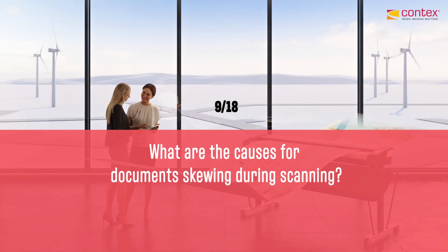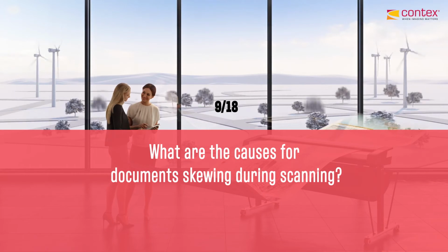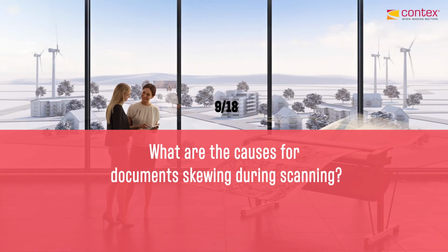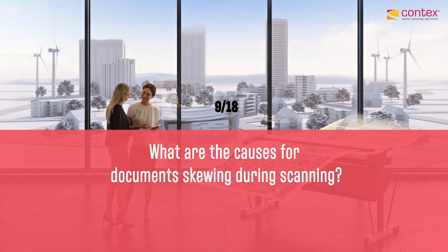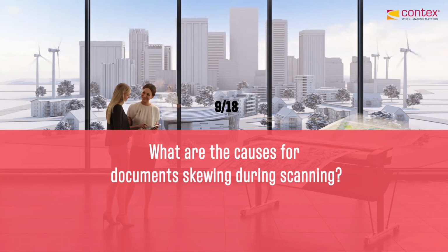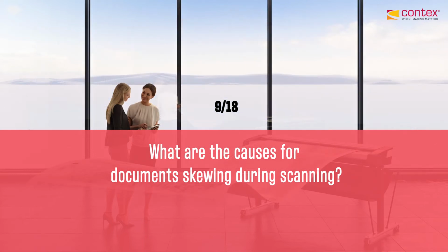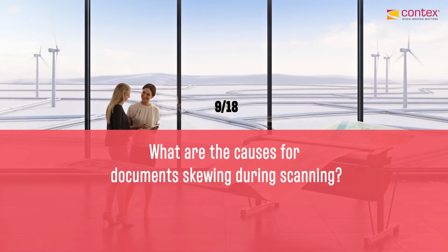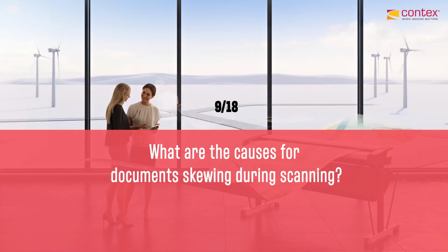Yeah, I think that would cause a much bigger skew than just a little bit, but still, just make sure that lid is clicked in. Right. And for scanners with either an ATAC system or an OTAC, you want to make sure that the guide plate's lowered. Someone could have come in and scanned a piece of gator board, and it's raised. He didn't get it lowered all the way, and same basic principle there.